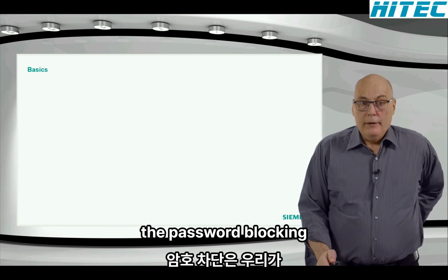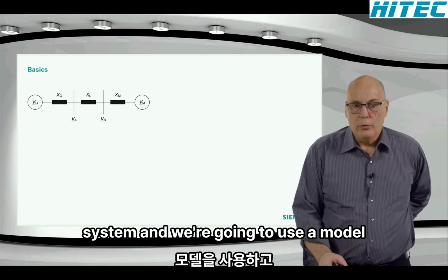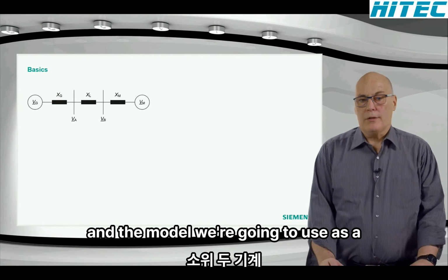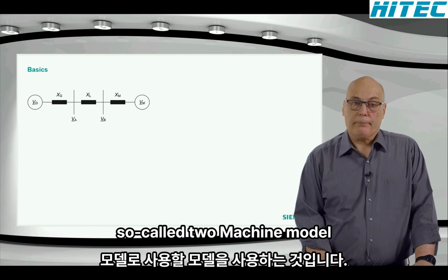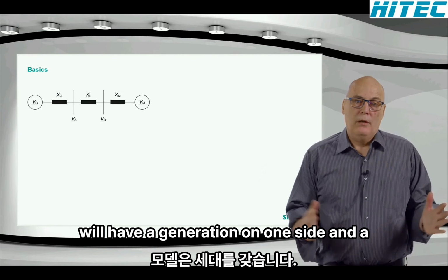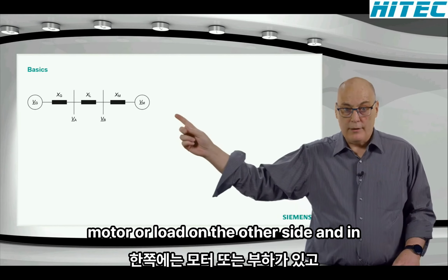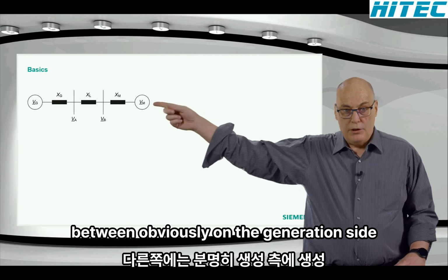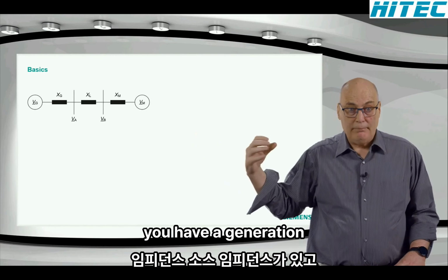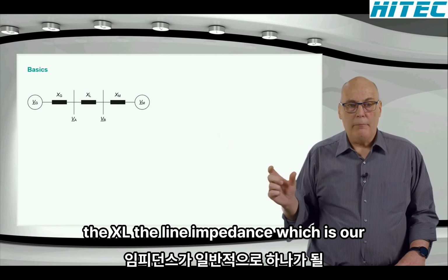Power swing blocking is something where we again look at the system, and we're going to use a model. The model we're going to use is a so-called 2-machine model. In this case, a lossless 2-machine model, where we have a generation on the one side and a motor or load on the other side. And in between, obviously on the generation side, you have a generation impedance, source impedance. Then you have the XL, the line impedance.